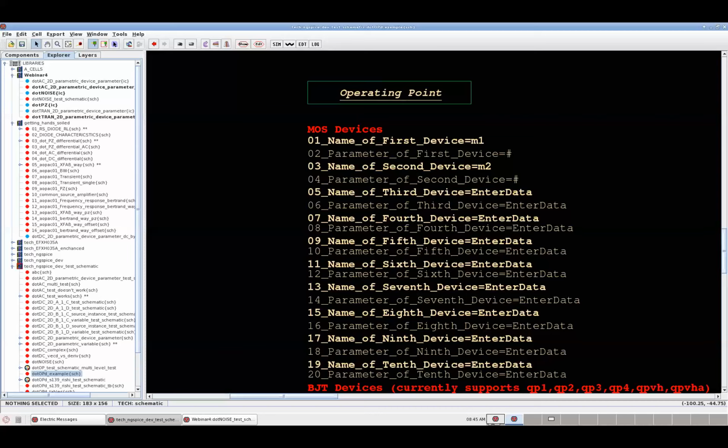do a cross, and for that cross you do .op, and that .op is going to save the operating point. After you say .op, the next thing you say is .ac. So it is going to stop there, and at that .op point, it's going to run a .ac analysis. Yeah, it is more of a SPICE or ngSPICE code based solution rather than a template based solution. But yes, I'll have to definitely look into that. I got it. Thank you.